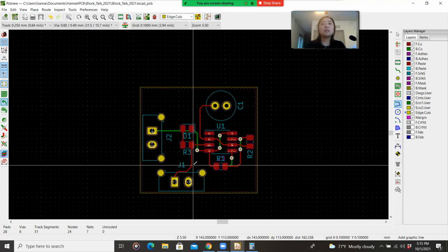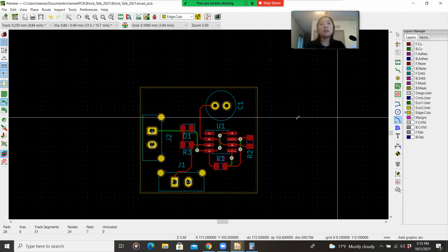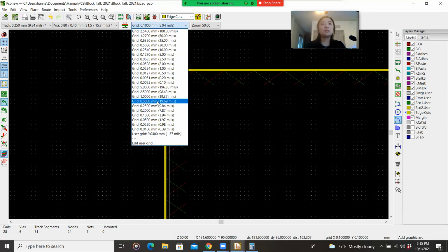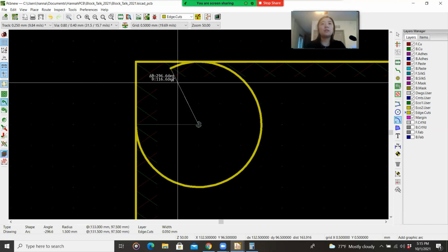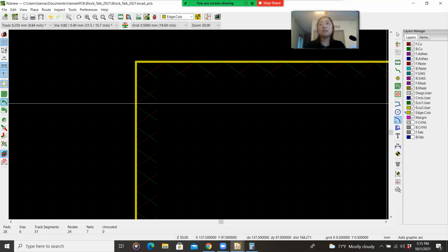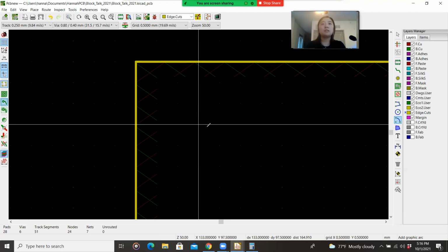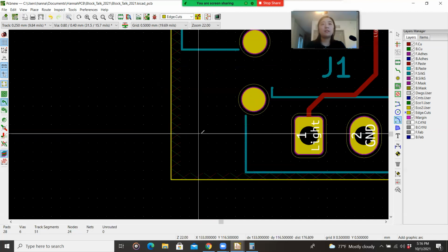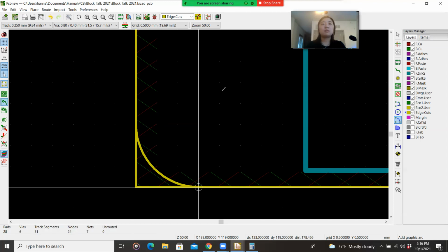Now one thing though is that those corners end up kind of pointy. So what we like to do is create rounded corners. Let me make the grid size a little bigger. Let's go ahead and do that. You hit this arc button, and I like to make sure that it's a square, so just make sure that it's even. You go the same amount up and down. Sometimes it's trial and error on which direction it goes in, because I often forget. But go ahead and do that. I like to make it consistently the same round corner on all ends.